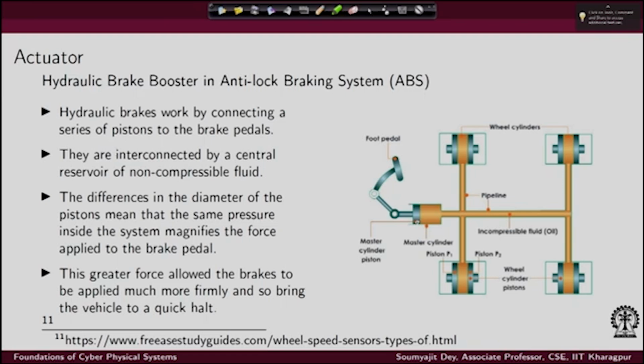Again, this is a high level view, but it provides you with an accurate enough example of how an actuator works, because you can understand that the real pressure on which this system can operate will have a lower bound and upper bound, okay? That would also mean that the software signal that should come in a real life ABS should also have lower bounds and upper bounds, and those will be the variable bounds inside which a practical brake pressure should be available.